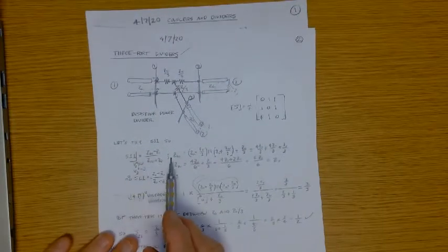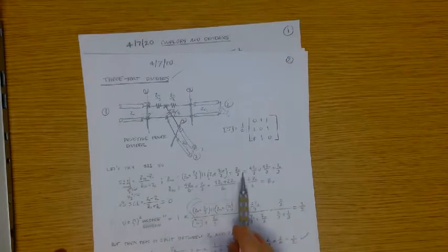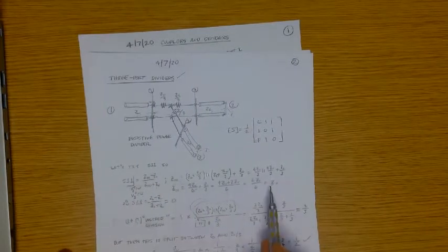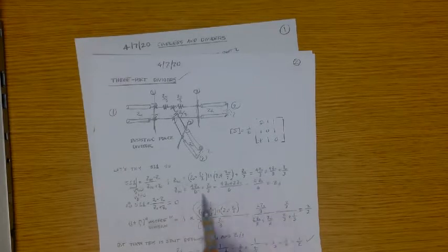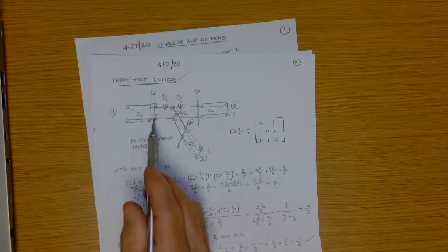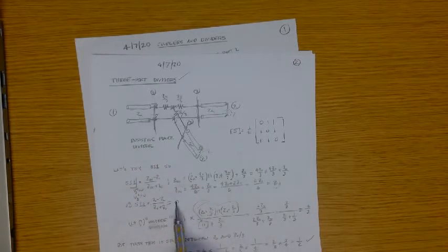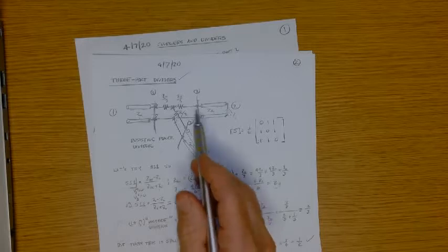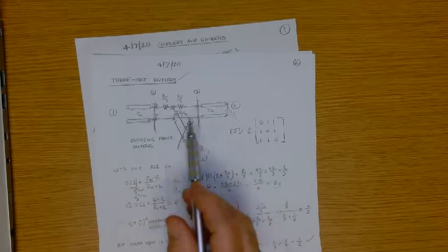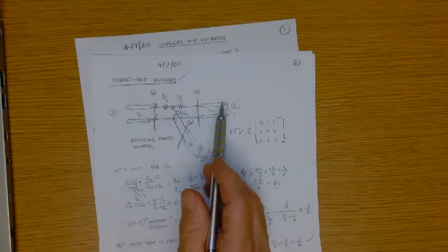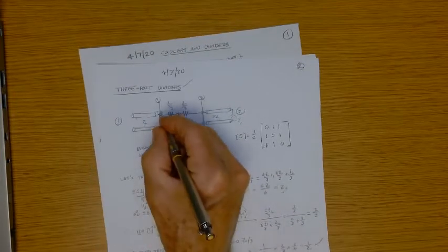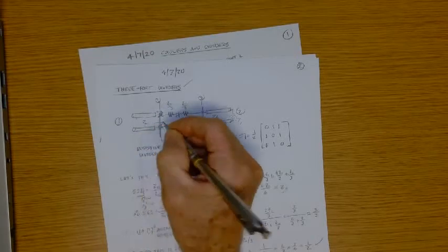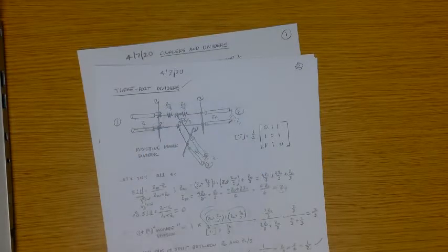So, right, that's pointed out here. So Zn is essentially, we can argue and demonstrate here, Z naught. And so when I compute the reflection coefficient at this point, as expected, we get 0. So all that circuit theory and transmission line theory did indeed show us that the input impedance at this location was Z naught.